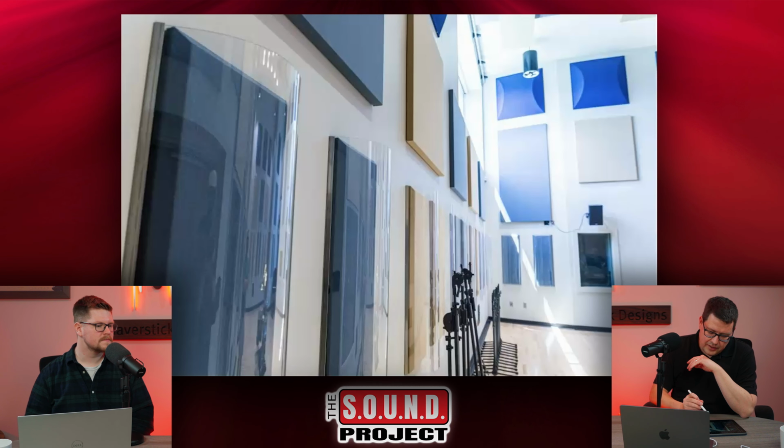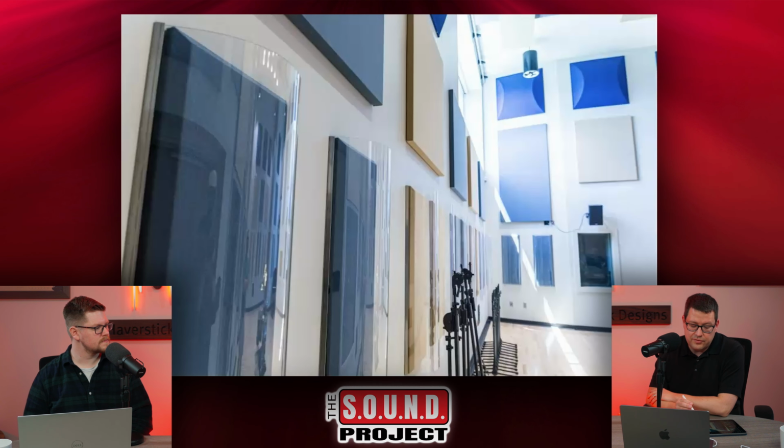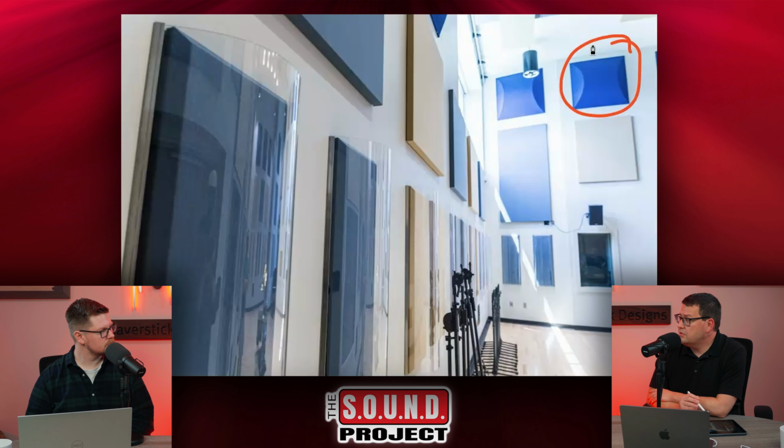Let's see. The next one here is Kent State University in Ohio, and we've got some barrel diffusers up here, high up on the wall. These would be an example of a geometric diffuser, just a barrel shape that scatters sound pretty evenly. Polycylindrical diffusers were really popular back in older studios, where it's an easy thing to create.